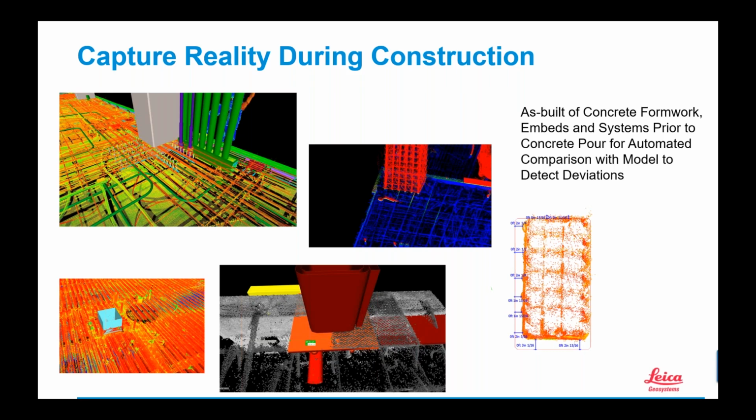Or during construction, before the pour of the pad, I can do a quick scan. With the Leica scanner, it takes about 28, we'll round up, we'll call it 30 seconds to do a scan, and about 5 minutes to bring that in, to overlay it, to do a sleeve analysis. Is that sleeve in the right location? Yes or no? And if I can move the sleeve before it's poured, it's a couple hundred dollars based off past experience last year.